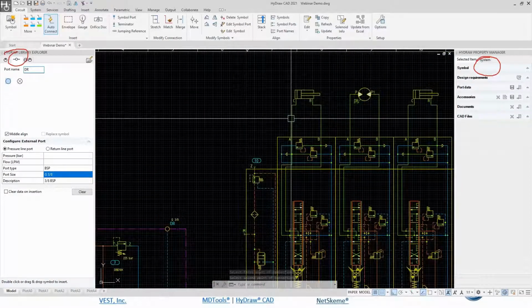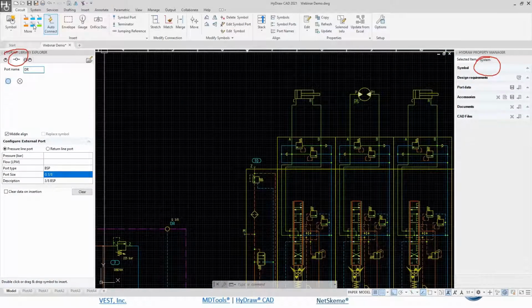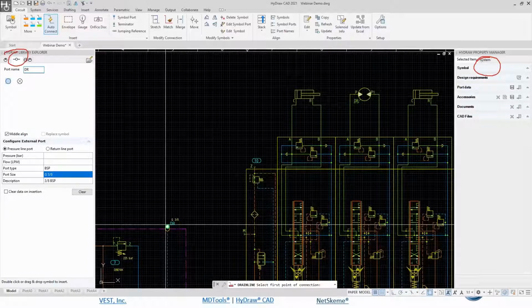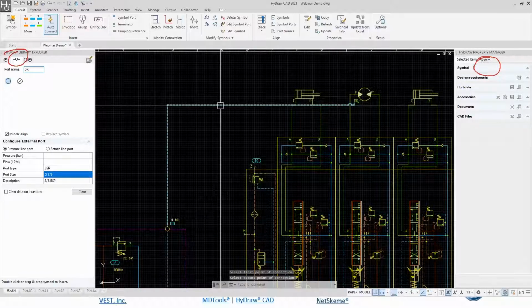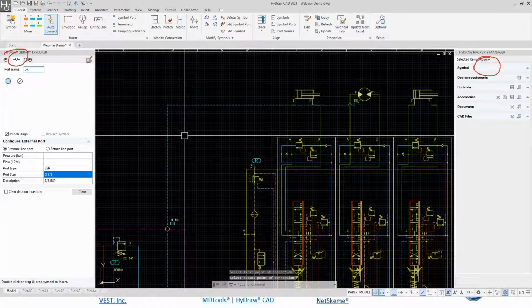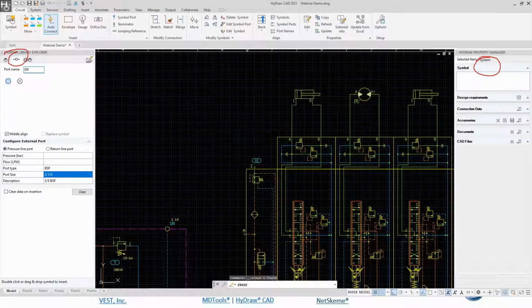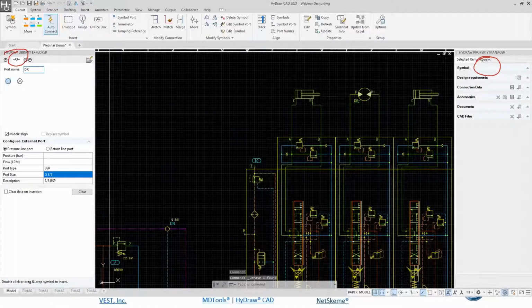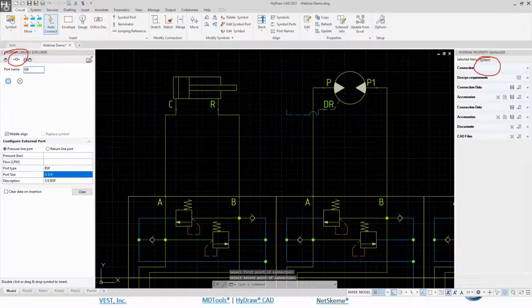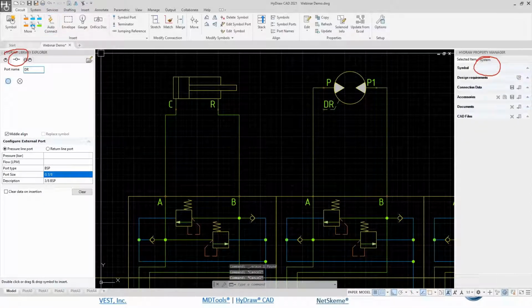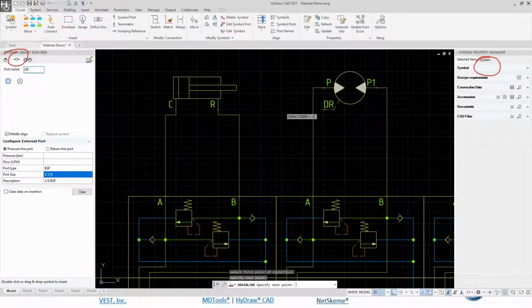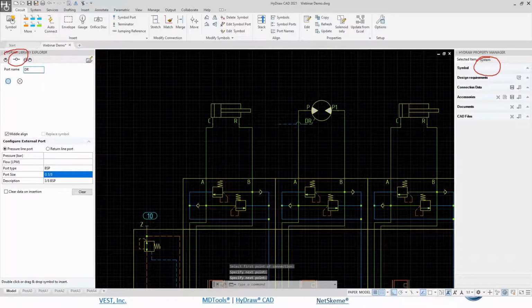If you don't want to have a connection line going through, like in this case, if you don't want to have longer segments of lines, you can just add the jumping reference. To add the jumping reference, you must have a line segment. Let me make just a horizontal segment here and the vertical segment here.